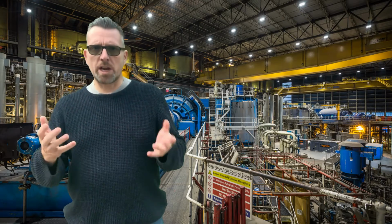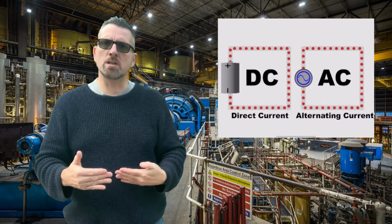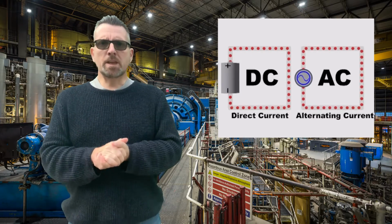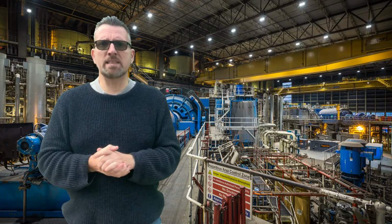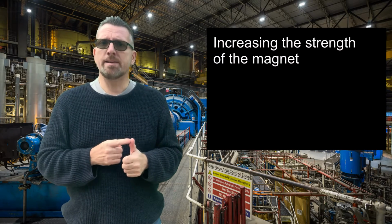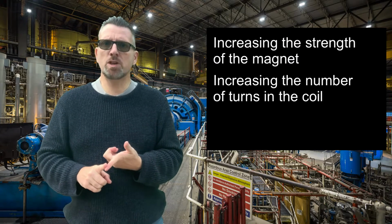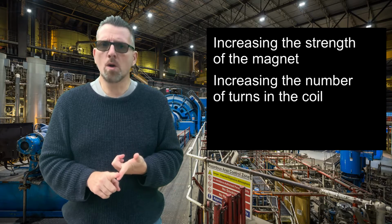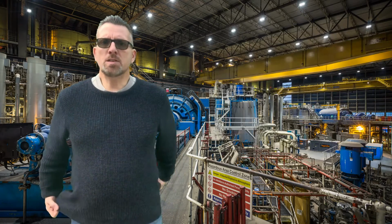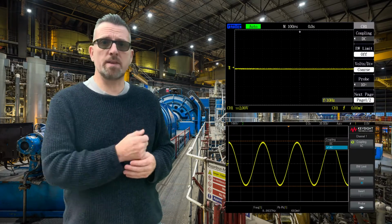Now, dynamos, or generators, produce a current that changes direction every time the magnet turns, and this is called alternating current, or AC for short. Now, the current supplied to our homes is AC. The current and the voltage of a dynamo can be increased by increasing the strength of the magnet, increasing the number of turns in the coil of wire, or by increasing the speed of rotation of the magnet. You can see how AC and DC current differ by displaying them on an oscilloscope. They look like this.